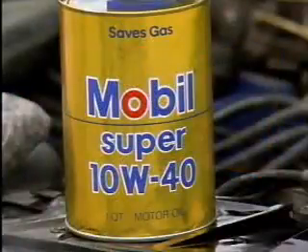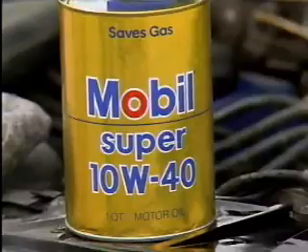In low-temperature applications, lower viscosity oils are usually more suitable. They flow more easily at low temperatures and can reach moving parts better than thicker, high-viscosity oils. In high temperatures, a thicker, high-viscosity oil is usually needed. The oil has to be thick enough, that is, have a high enough viscosity to maintain a film over the moving parts it must protect. Many oils, of course, have to be able to lubricate in both low and high temperatures.